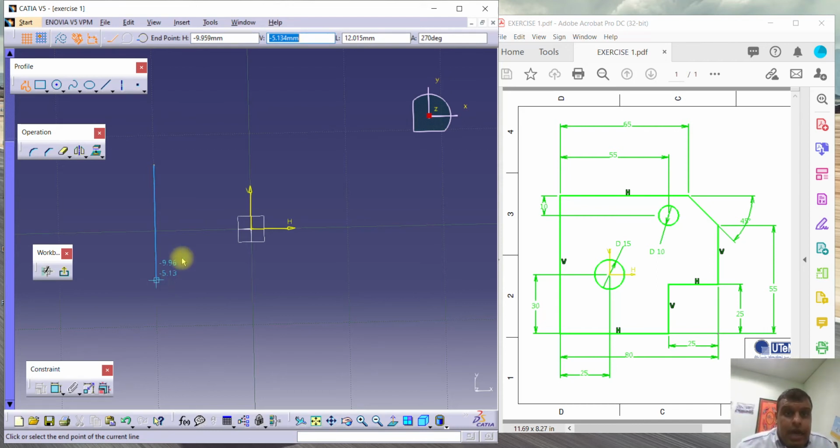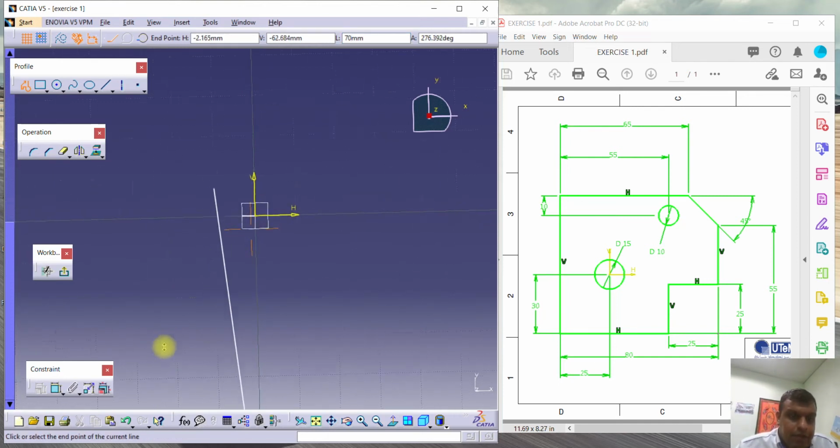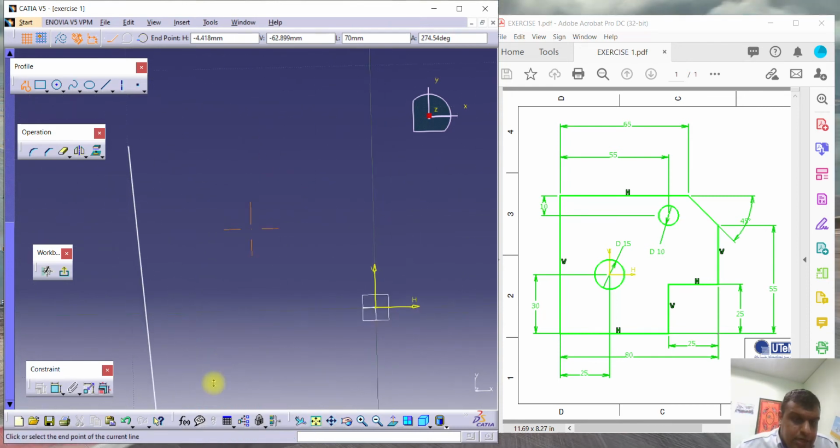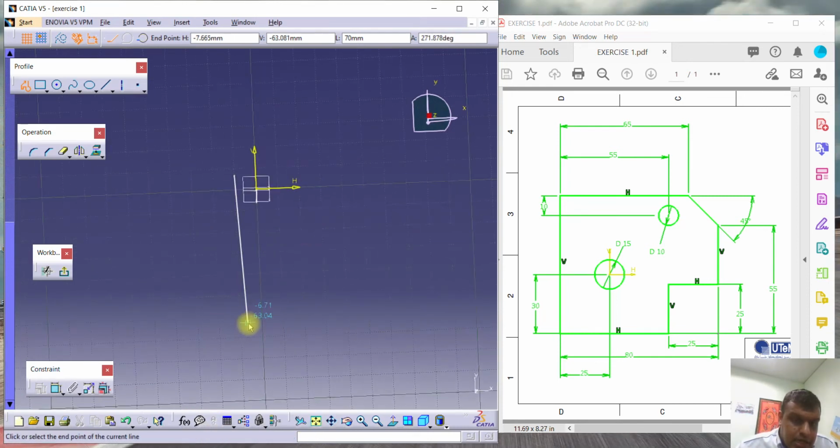At the sketch tool, you just click tab until the length. Okay, now your length is 70. You put 70, enter, and then after enter, you make sure the line is blue color. Blue color means the straight line. Okay, straight line like this.